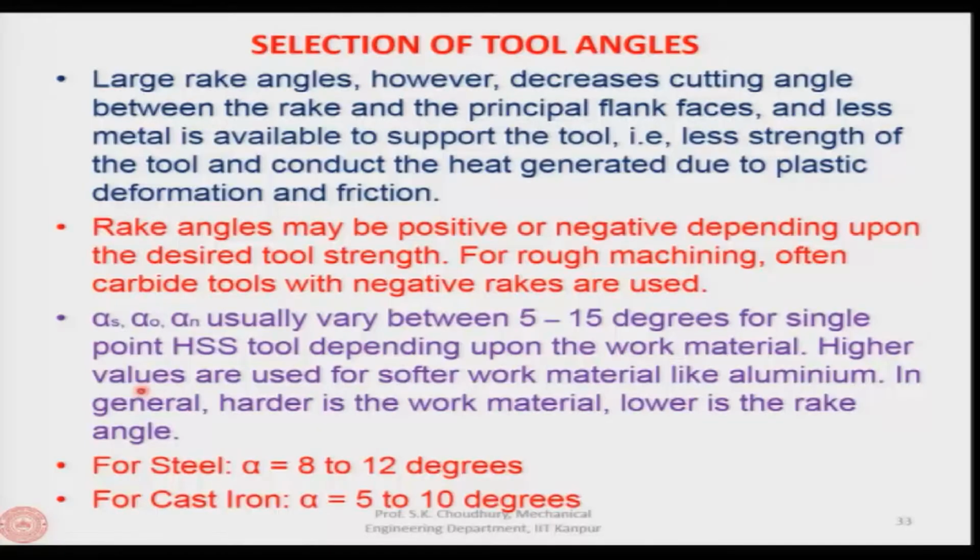Higher values are used for softer work materials like aluminum, because with softer material the force will be less and the power consumption will be less. Therefore, you do not need to have high strength of the tool, so large values can be used.